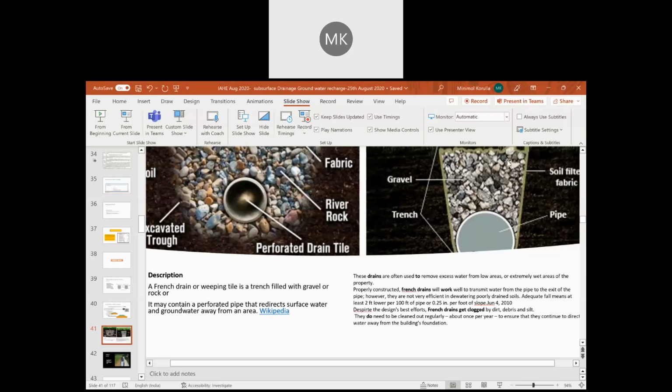But I think the expert committee now working on the revision is really considering revising that. A small correction is required for the drainage geocomposite. I will tell you what it is. As I told you, a drainage geocomposite is a combination of a drainage net sandwiched between two geotextiles. So the strength of the individual member as well as the composite is being given. Drainage net, geonet property, geotextile property, and the composite property are all there.